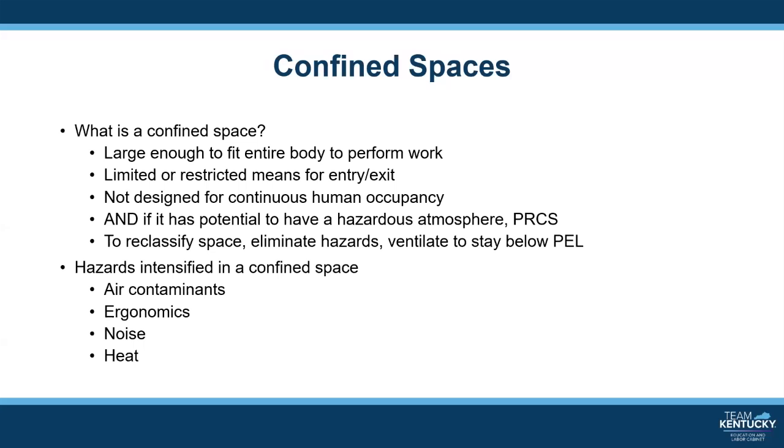If the proper ventilation is not possible, the welder must use appropriate breathing apparatus. The respiratory device, however, must be independent of the ambient air inside the space. Therefore, suitable breathing protection is not provided through a filtering and breathing device. Rather, exclusively self-contained respirator devices with hoses connected externally.